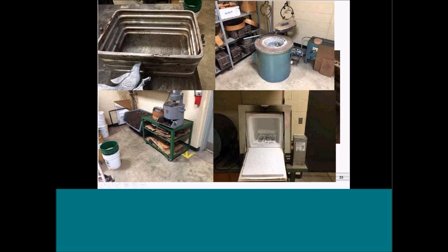This is my sand that we actually have, and this is a machine that will actually break up some of the sand. We keep using the sand. This is a muller. All right, we keep using the sand. And I think I've replaced this sand. I've been here now 16 years, and I've replaced it 2 times. After so many times it loses its ability to stay together, and it really doesn't cost very much. I actually have several foundries around this area that I can get some materials from. There's a riddle that you use across the top of it, and again, you see the various flasks. All right.